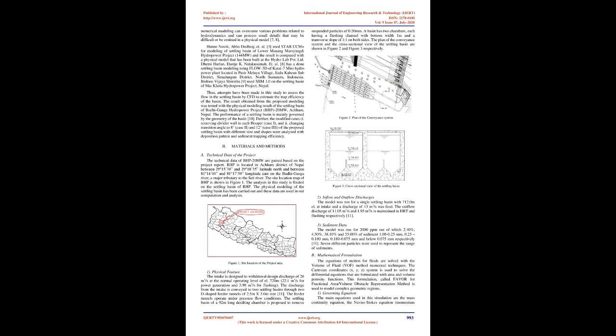The design codes for a settling basin are mostly based on empirical approaches that may not provide accurate results, as there is strong impact on the water velocity distribution and the degree of turbulence in the settling basins, that is due to different geometry and inflow conditions 3, 4. Thus, to provide accurate result, certain site-specific modification is required. The effect of the geometry is difficult to execute in 1D parameters in the analytical approaches.